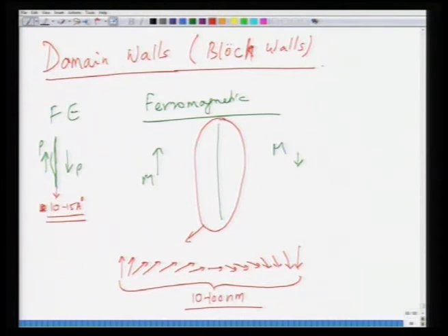So, there is a gradual change of magnetization at the domain boundary, unlike in the ferroelectric material, and this actually results from the change in the way the domain reversal takes place. In case of ferroelectric material, we looked that the new domains nucleate, which are in the direction of applied field, and they grow at the expense of these older unfavorably oriented domains.